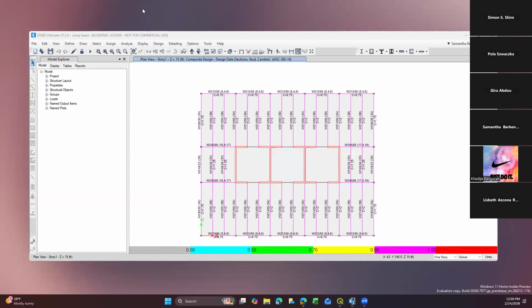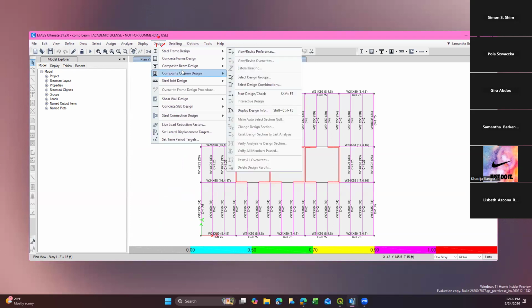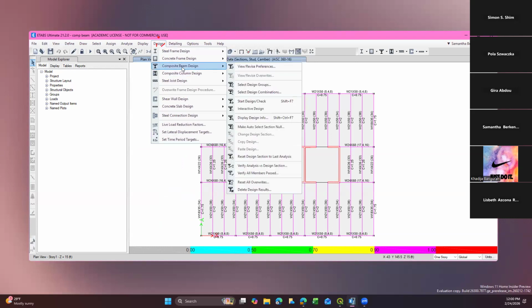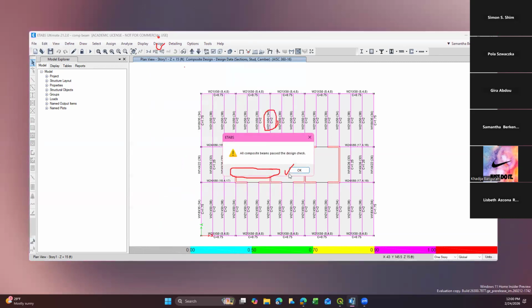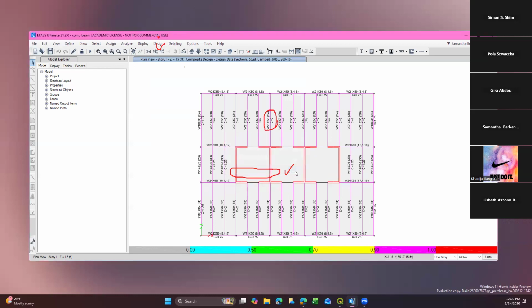Now, I'm going to point out again, everybody pay attention. Go to design. Otherwise, you're not going to keep these sizes. Once it tabs, choose member, go to composite beam. You need to do this: verify all members. Click it, then say okay, and then rerun it.